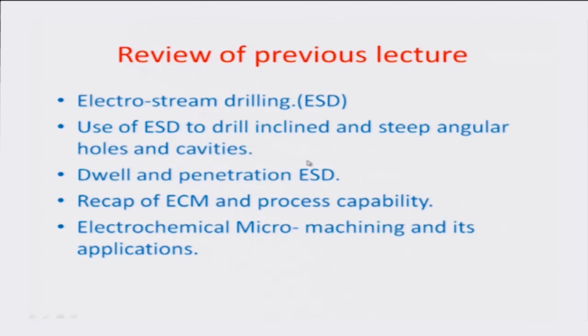We also talked about the two different variants that ESD has, called dwell drilling and penetration drilling, depending on whether the electrolyte stream dispenser is static or is moving at a constant rate or constant feed towards the workpiece.